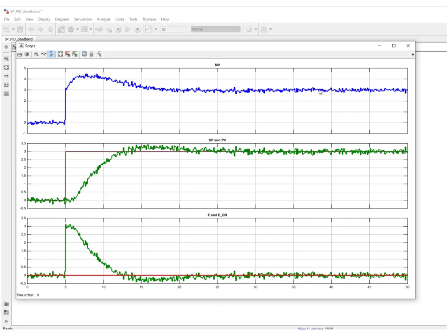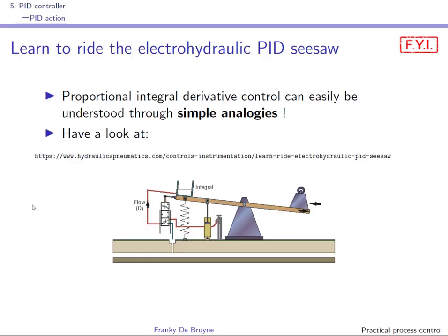The alternative is of course filtering, but as you know, filtering is going to cause a phase shift in the signal, so it's kind of a trade-off what you will do, filtering or use a deadband, and it will depend on the type of application.